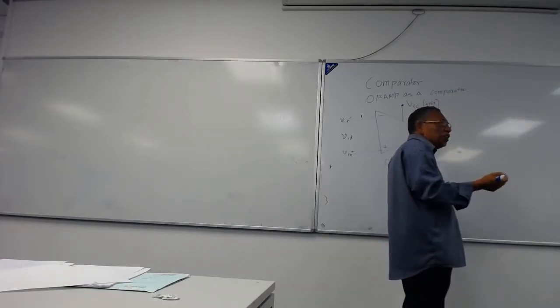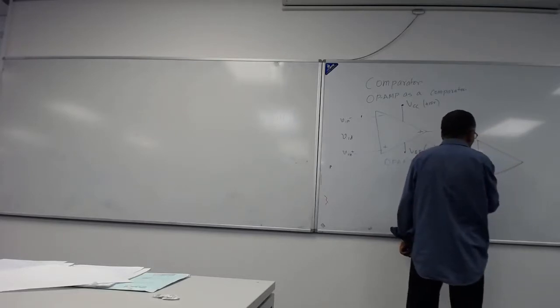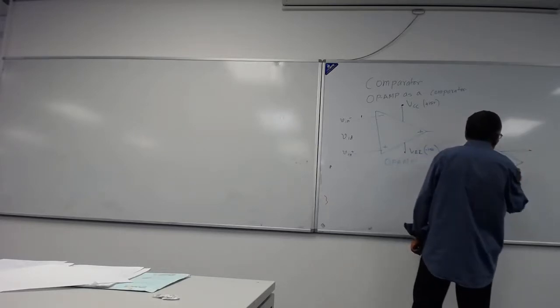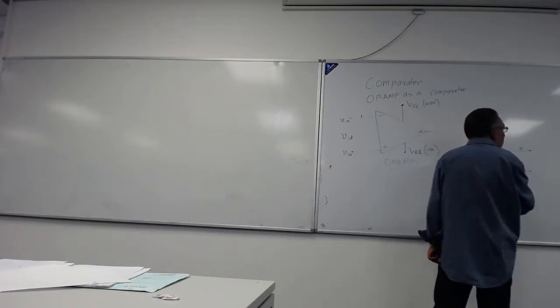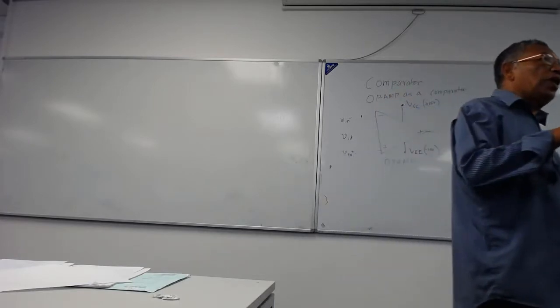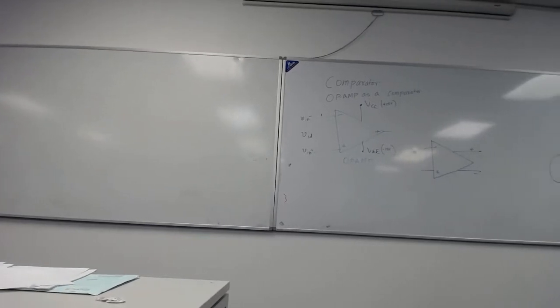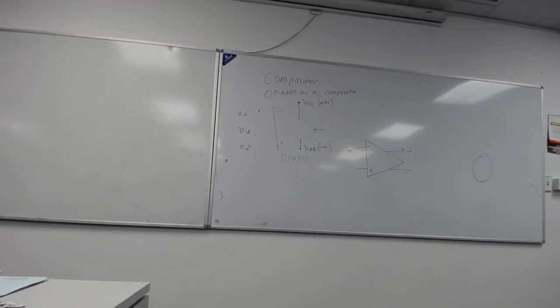In many cases, particularly in integrated circuits, you can have a minus here, a plus here, and then you can take two outputs out of here, a plus and a minus. When you actually build the transistor circuit of an op-amp, you'll see that it naturally comes with two outputs, a positive and a negative.